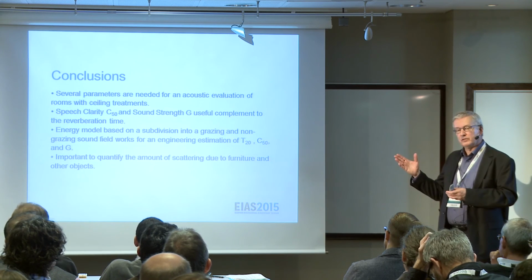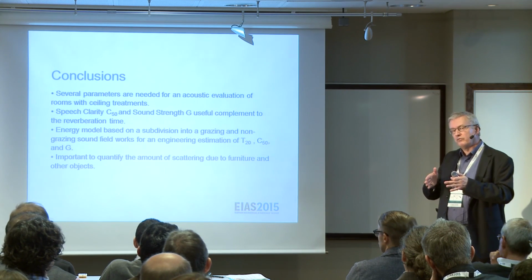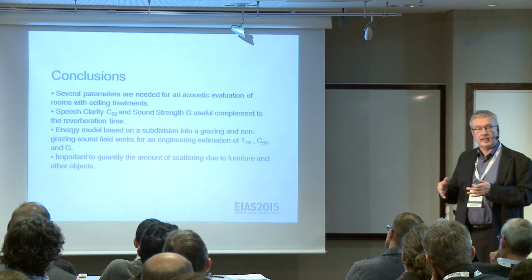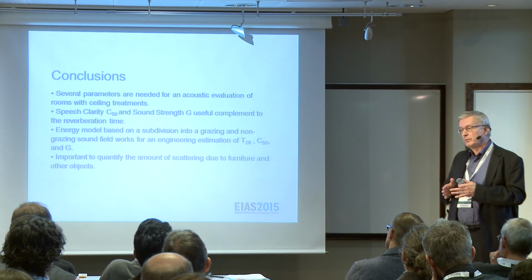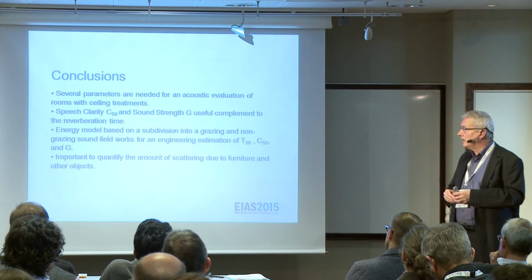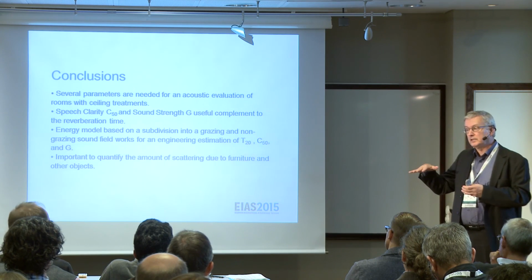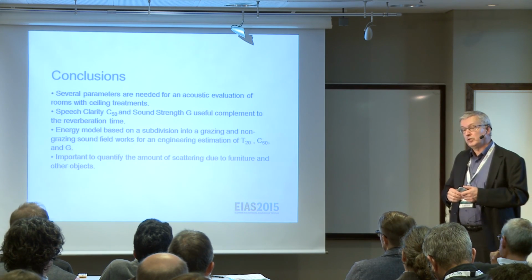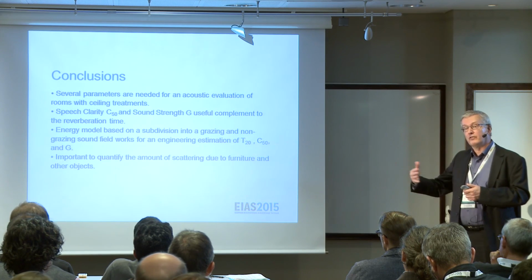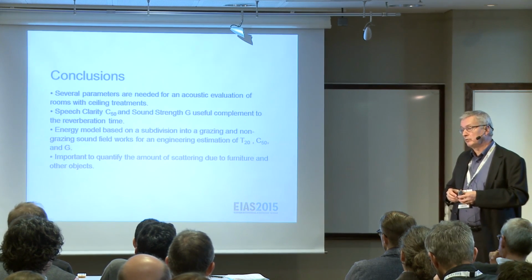But there are other examples of standards where you get closer to, so to say, the real situation. Like in ASTM, we have methods for measuring articulation class and such, where we build this type of mock-up. And I think to measure scattering, we can use this type of rectangular room with a highly absorbent ceiling and measure the objects and then define a sort of alpha scattering per object. And then we can use that in this type of model.